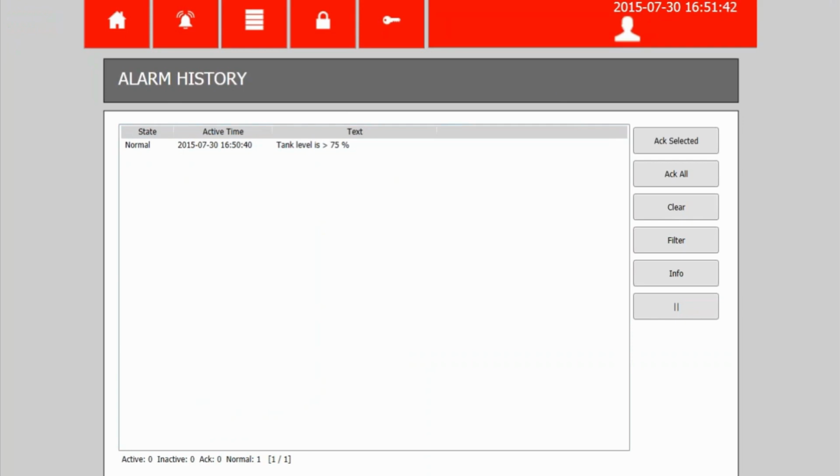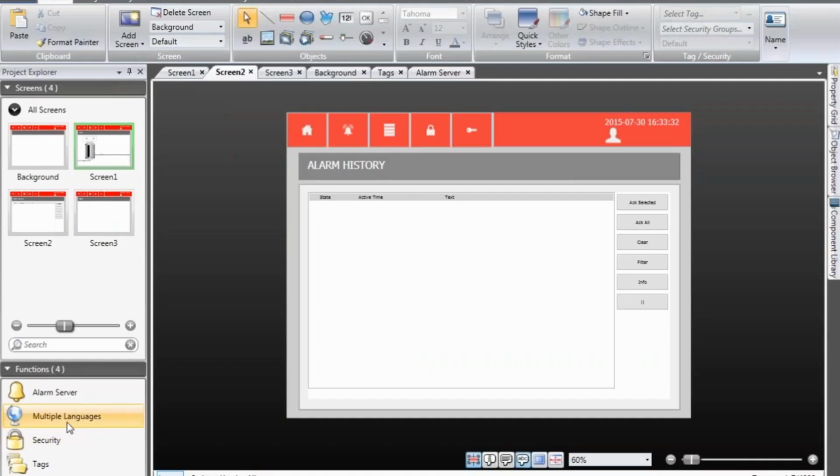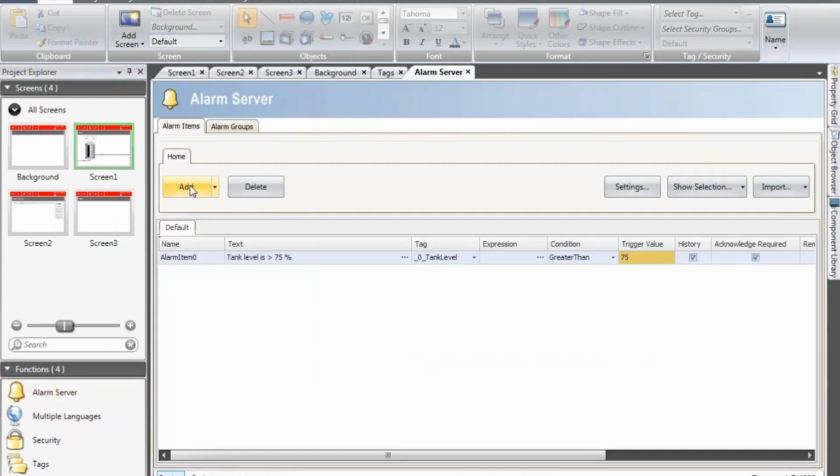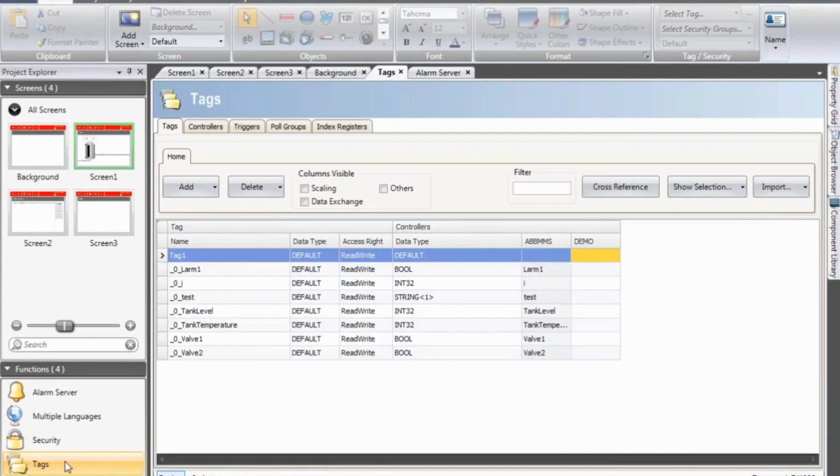What we will do now is do it the opposite way, letting the controller trigger the alarms, and we are just subscribing and updating accordingly. So I remove the panel-generated alarm, and instead I need to tell the controller driver that it should start subscribing for alarms as well.